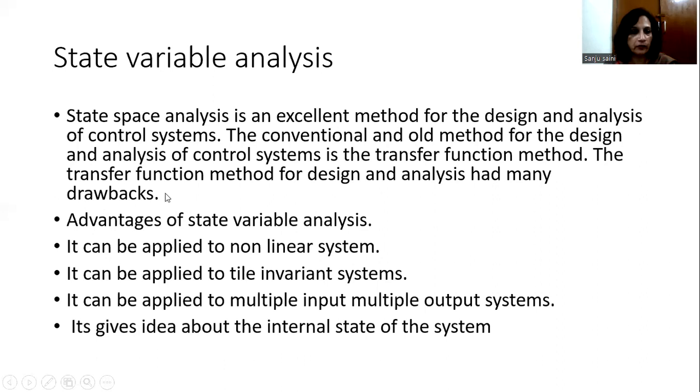Like, the transfer function approach cannot be applied to the nonlinear system, but the state variable approach can be applied to the nonlinear system. Transfer function can be applied for modeling only time invariant systems, and the state variable analysis approach can be applied to time variant systems. I'm sorry for the mistake over here. Then the transfer function approach is applied to single input, single output systems only, but the state variable analysis approach can be applied to multiple input, multiple output systems. And transfer function is not giving any idea about the internal state of the system.